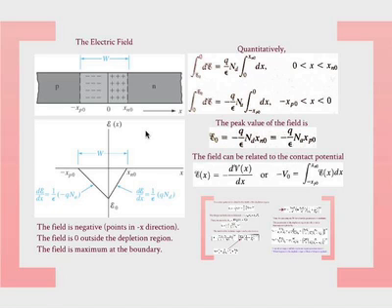That's the unit charge per unit volume multiplied by the volume. What's the volume? It's the cross-sectional area multiplied by the length. So it's pretty obvious. You don't need to actually remember anything. The area, in this case, is just pi times the diameter squared over 4. The cross-sectional area is given. So that's the total charge. Positive charge is equal to the negative charge, so it's just one of those.